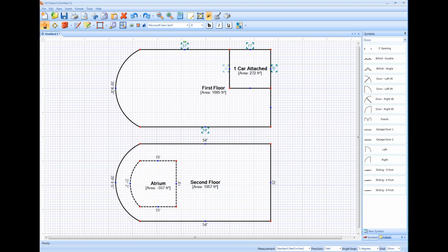Another neat trick you could do is using the V or H for vertical or horizontal, you can change the alignment of all of the selected items. H makes them horizontal, V aligns them vertically. So to review, that was using the Control key on my keyboard, hold that down, and left click on various items to multiply select them. Another neat trick you can do while you've got them selected is hit the plus or minus keys on the keyboard. You'll see that as I hit the plus key, that font increases and the minus sign decreases them.